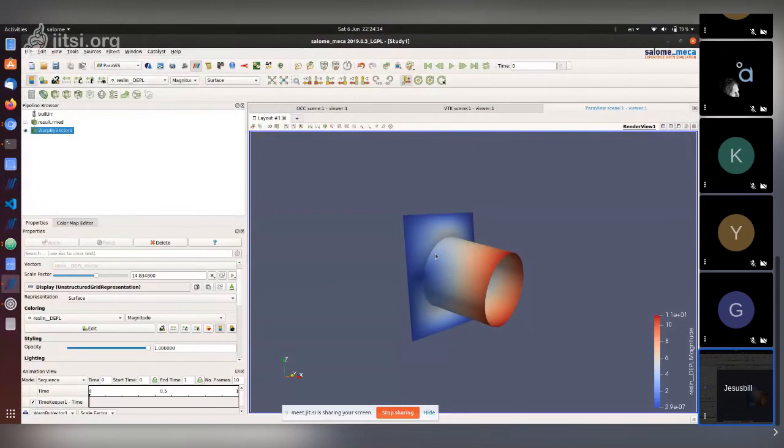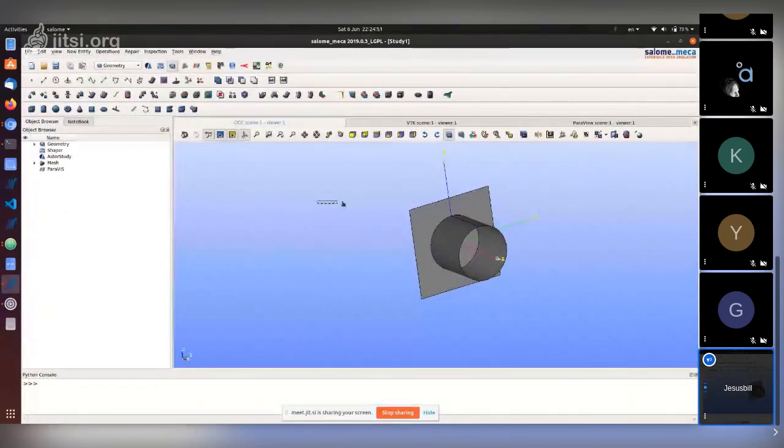A lot of things are feasible, although a little bit complex. I guess you would need a solid geometry, and then it depends what you want to do. If you have the parts that I created in the beginning, if you have more parts, as long as you do a partition, then everything is bonded together, and if you are modeling also the welding, you can see the stresses in the welding and so on.